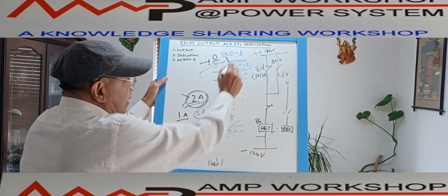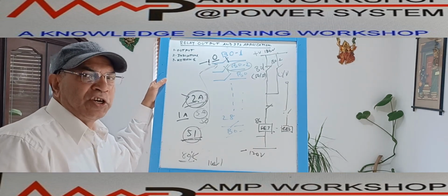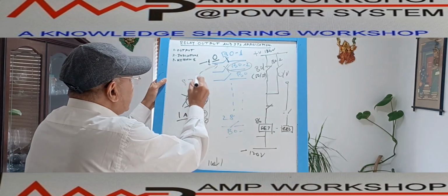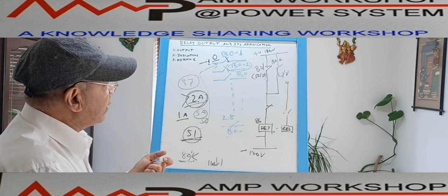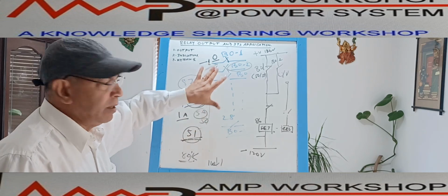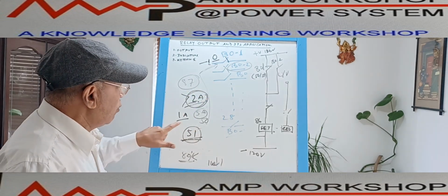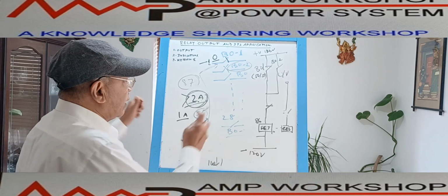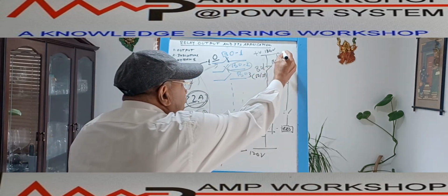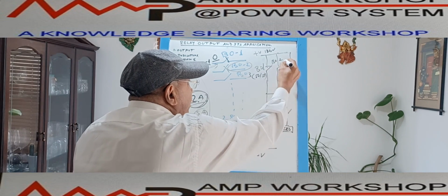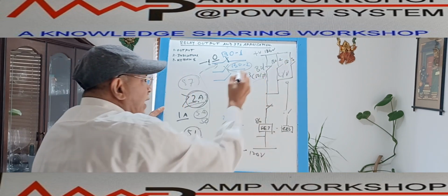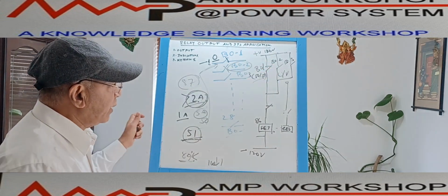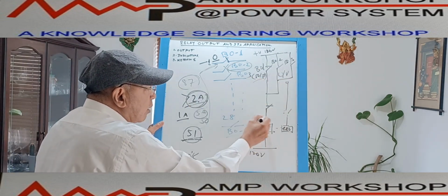This way, suppose this is a differential, this relay also has a differential protection. So suppose 87 is operating, the moment 87 is operating, differential protection operating, this protection function is operating in this relay, we assign that when 87 operates, this will activate the B03 contact. So we'll put another here, it is B03, it will come over here. That means when an overcurrent condition exists, or under voltage, or differential operated, in any of these cases, immediately this lockout relay will operate.